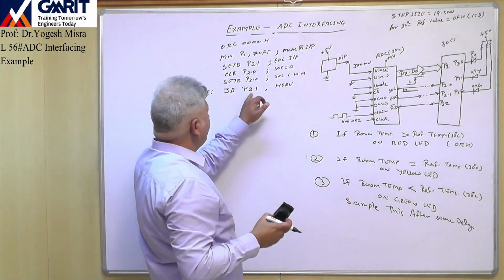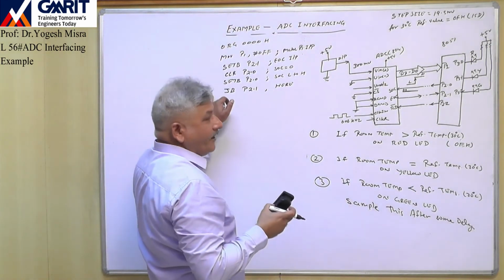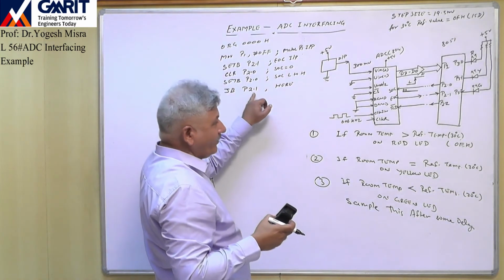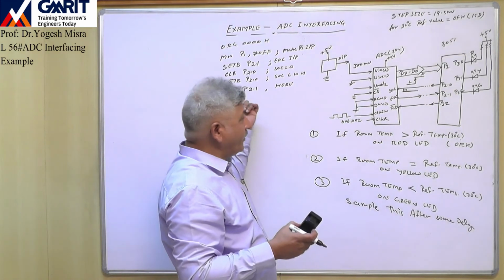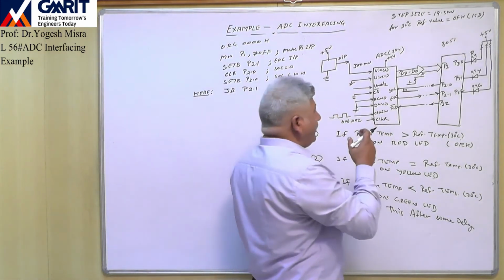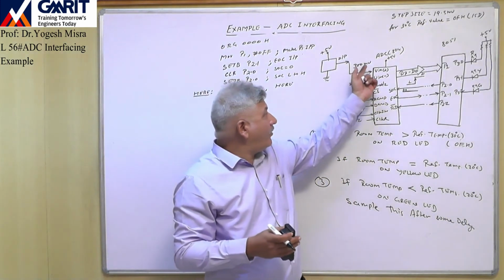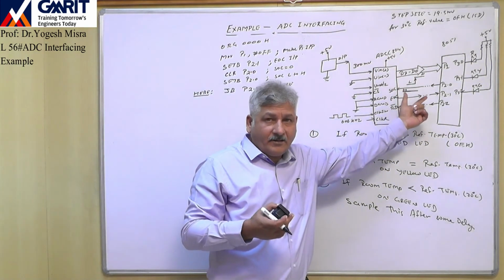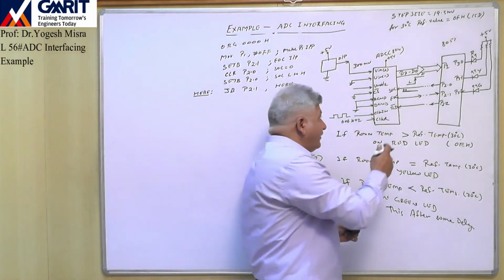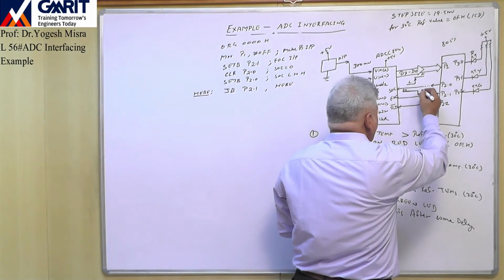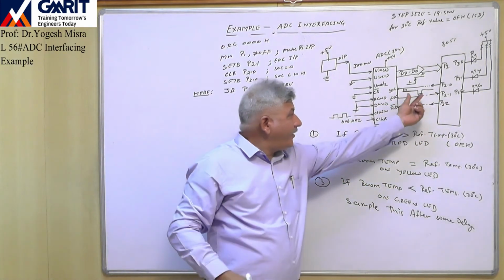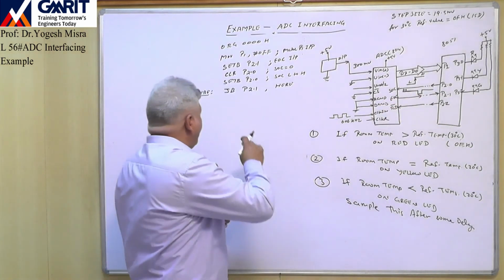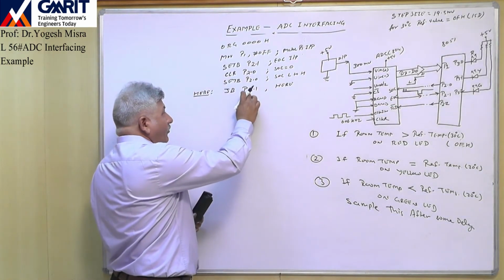So if this pin is 1, again come to the same place, again you check this pin. So it is high, and the controller will check this pin continuously. And the moment our conversion from analog to digital completes, this pin will go low for a small duration, and again it will come back to the high position. So the moment this pin goes low, what will happen?